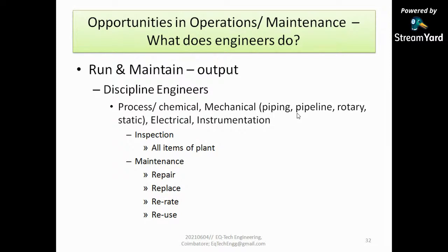So I can rerate a pipe or equipment to a higher pressure or a higher temperature, and you can continue to use it. It depends. Sometimes the rerating may not be possible. And inspection will tell whether the equipment or piping is fit for reuse, or if it is not fit for reuse, you have to replace or repair.